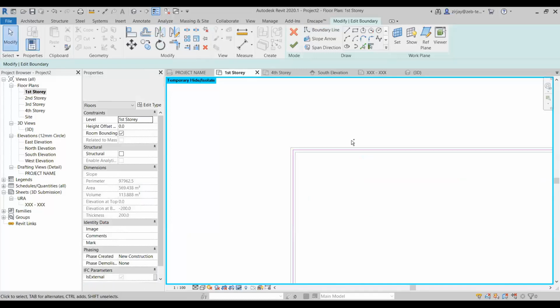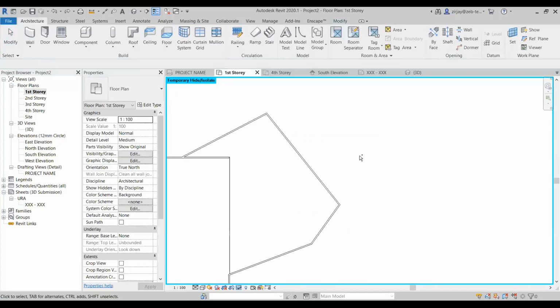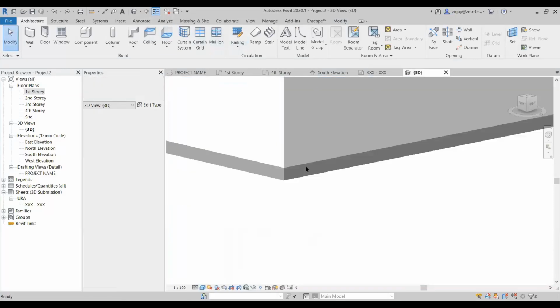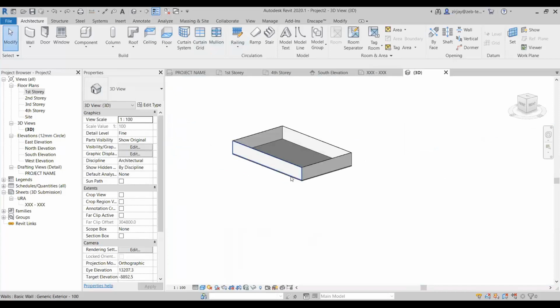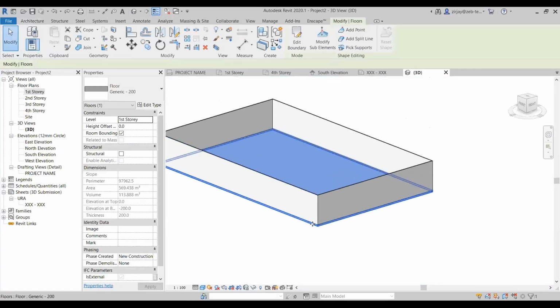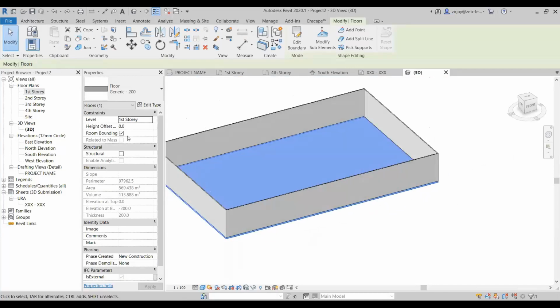Okay. Okay, so that's it for the walls. So after exterior walls, it's good practice to immediately draw the floors because you already have the outline of the building. So basically, the floor should follow the outline, the outermost part of facade of your building. Okay.